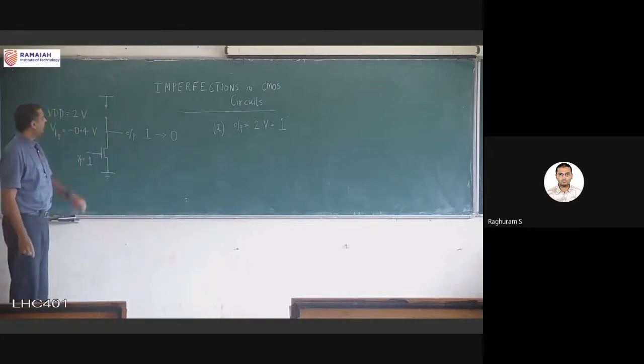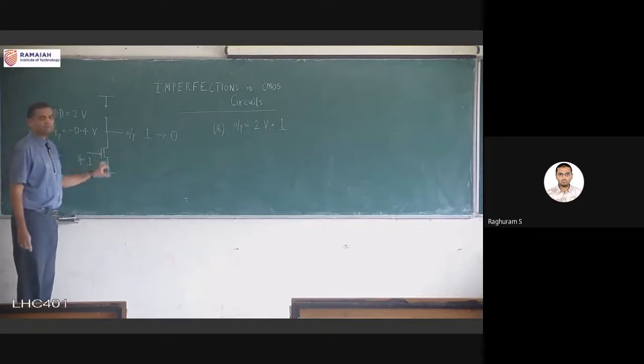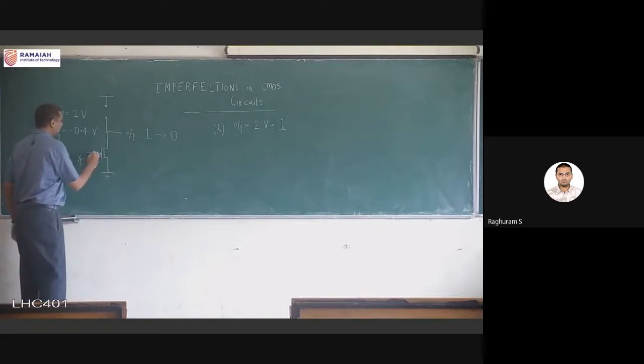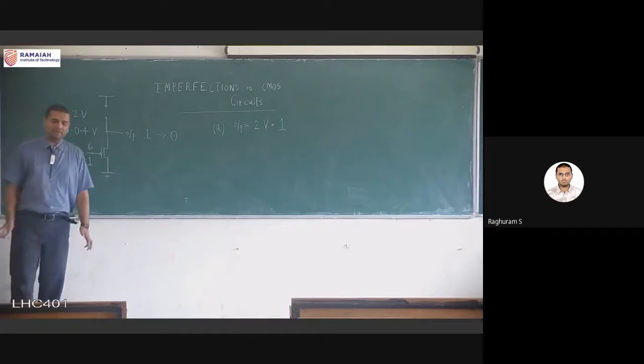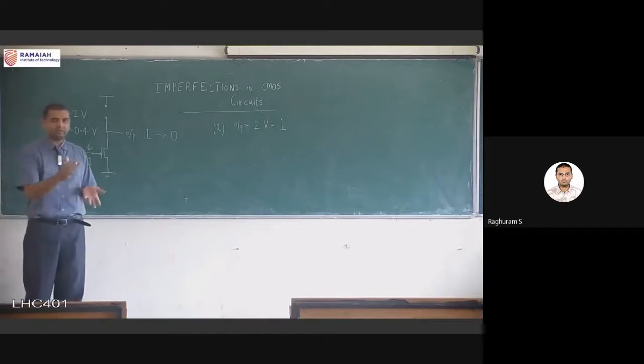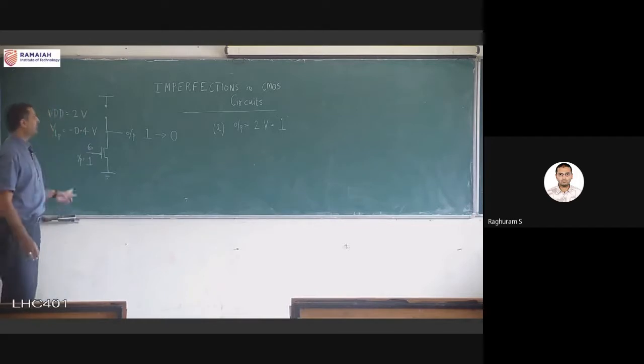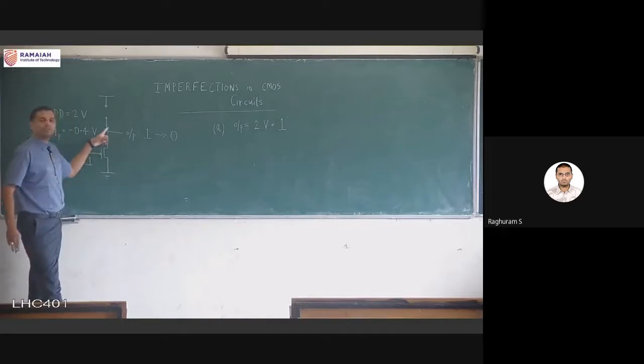Okay, and another thing, this is our situation, and we have to mark the drain and source terminals. Gate terminal, there can be no doubt. It's connected to the gate, and drain and source terminals we have to mark, and we cannot mark that arbitrarily. The drain and source terminals are related to the direction of the current plus the device type. So this is a case where there is some positive charge here.